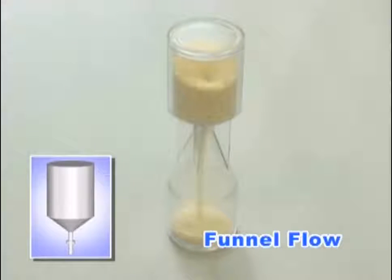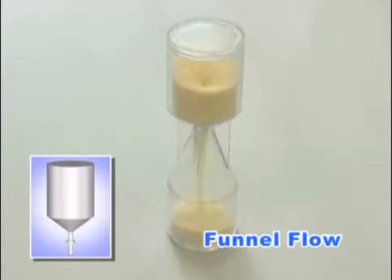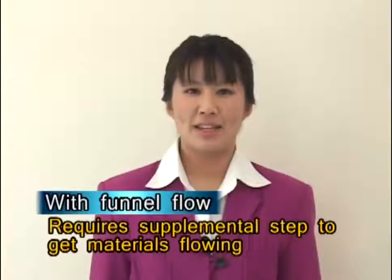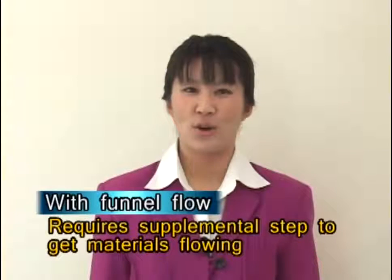Funnel flow generally occurs when flow is fast in the center and slow along the side walls. Only objects directly above the hole are released first, and the area around it crumbles and flows out little by little. Older materials are left to build up in the middle, creating safety and health problems. In other words, with funnel flow, to prevent blockage, some sort of supplemental step is required to aid in the flow of materials.